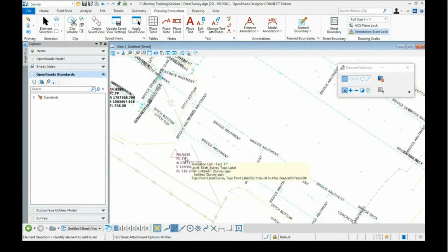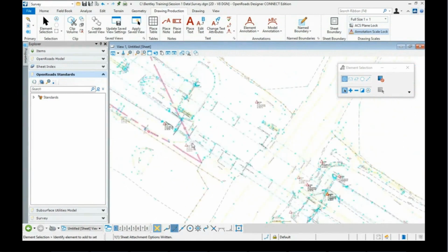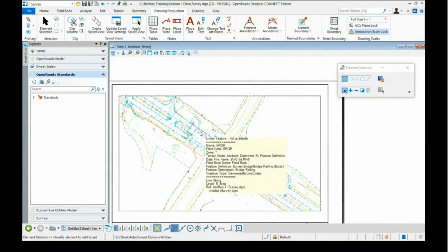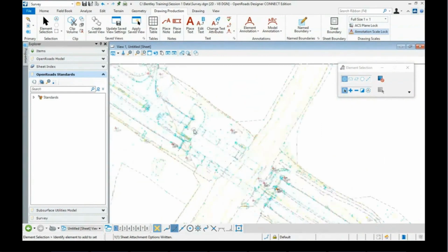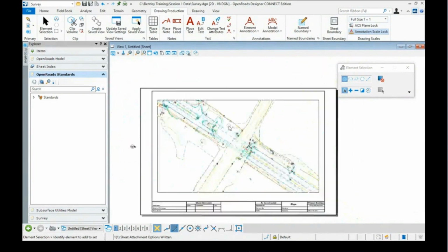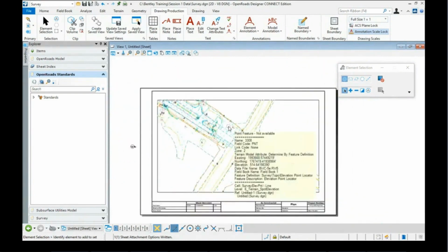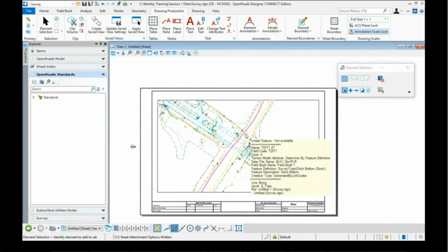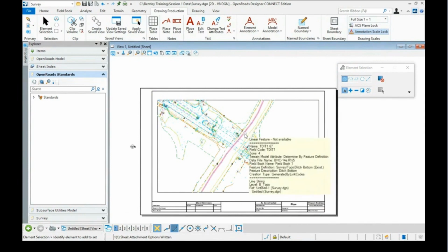So that is almost start to finish. We brought in raw data. We corrected the 2D planimetrics. We fixed up the 3D terrain. We got our terrain out to a separate file so we can send it to design. And then we did a little bit of plans production, just using the feature definitions that were already created on our elements. And finally created our plan sheet here that we can send out to plotting. All right, so that is kind of real fast through the basic survey workflow.